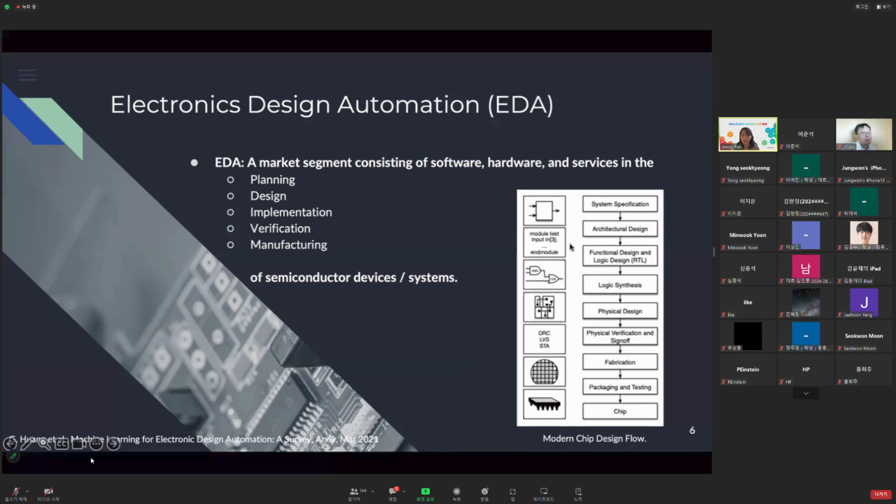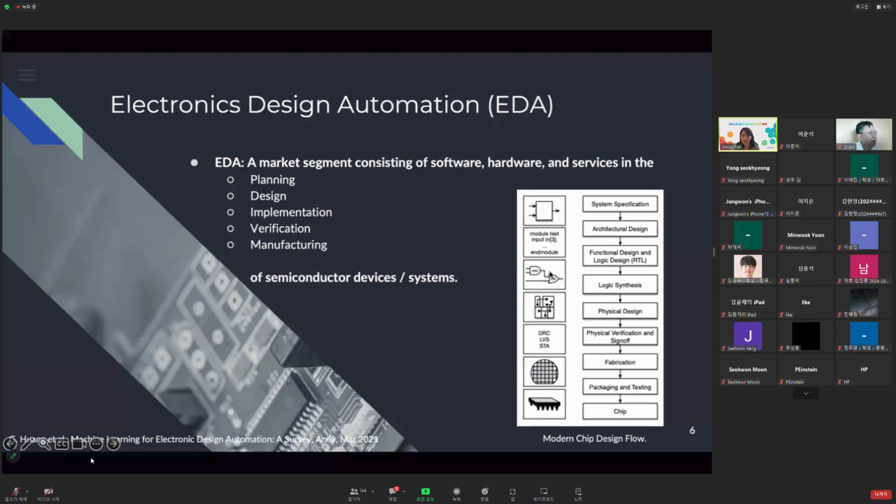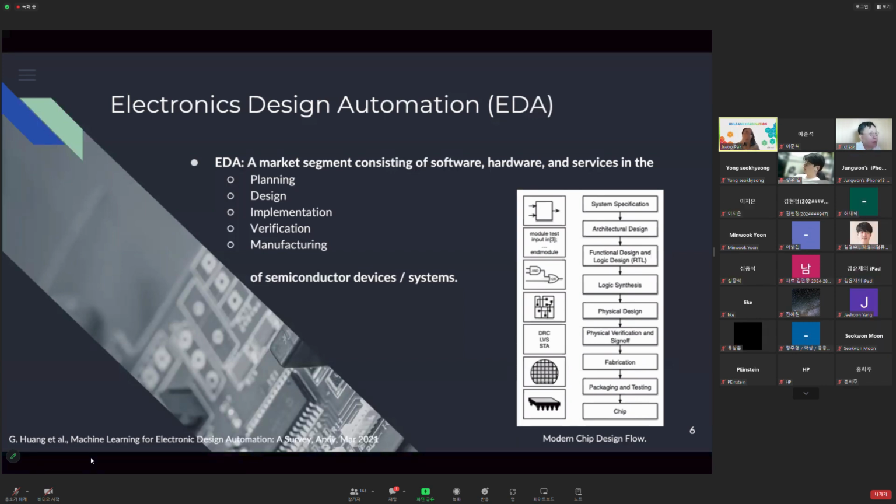Initially, designers or engineers will write some high-level code. It could start from C or C++, and then be synthesized into a hardware description language, and eventually into the logic design language. There are special languages to describe the hardware. And then there will be logic synthesis to make a netlist, basically a graph. After that, we need to place each of those components on the canvas and route them, making the connections. And this connection is 3D, by the way. It's not just 2D, so we need to use multiple layers, going up and down.